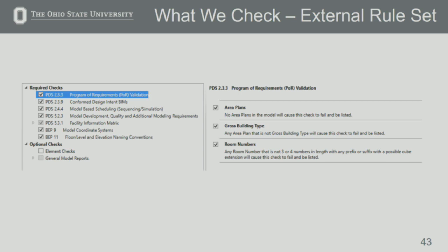And it's a very different rule check than the one that I just showed you. If you notice, the way that we numbered these lines up with the sections in our project delivery standard. It makes it easy for them to find where these problems might be from. In addition to this, we can't use the Revit model checker to check everything in our project delivery standard. That's true probably for both of us. It's checking a certain number of things that we can automatically check, but this definitely simplifies that process.